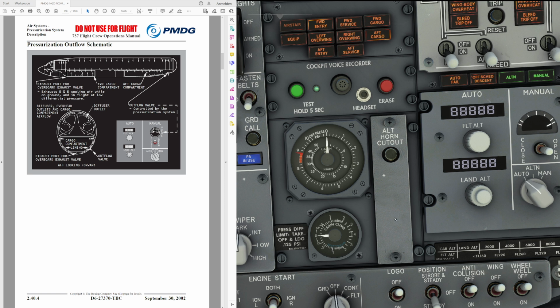There has been a case in my airline where this happened, and basically the pilots had a pressurization problem. They executed the memory items, switched the system to manual, and closed the outflow valve completely. But then they initiated the emergency descent without checking that the system is actually reacting properly. And in this case, the system did react properly, so it was simply a failure of the cabin pressure controller. But in manual mode, the system worked properly, so an emergency descent would not have been necessary in this case.